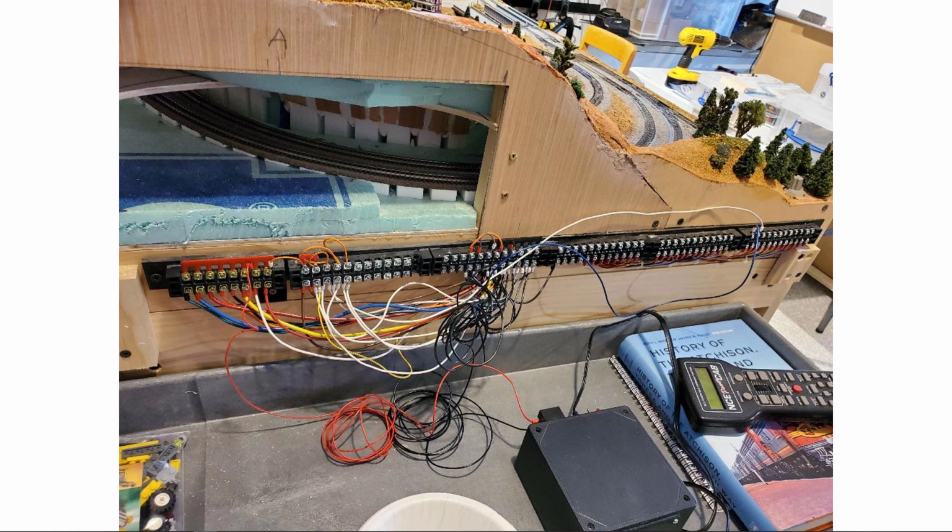And you can see, looking down on the bottom side of that terminal strip, look at those white wires. You see 2 under each screw terminal. This was when I was running the layout straight up with the NCE power cab that you see laying there. And then I had that power cab plugged into that black box there, and I have a red and a black wire going over, and I have all of one side of the track jumpered together, and all the other side, that's where all the black wires and a few orange wires are going. So I'm running all of the track off of one signal, so to speak. In other words, I'm not doing occupancy detection or current sensing.